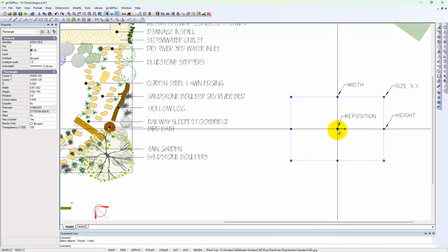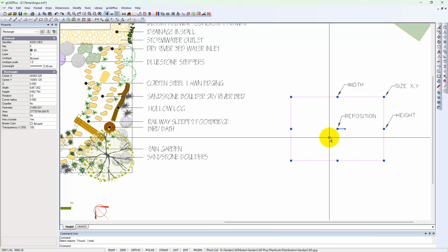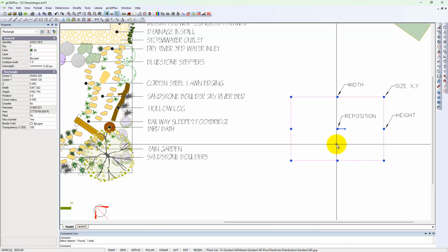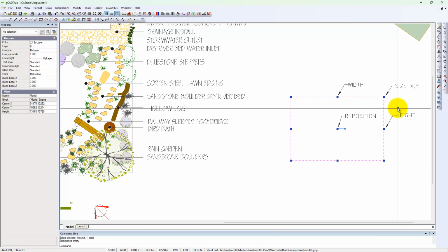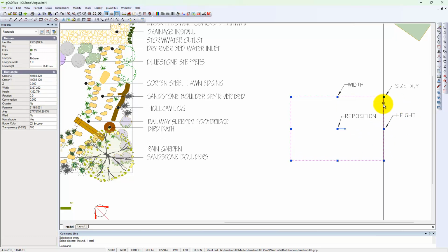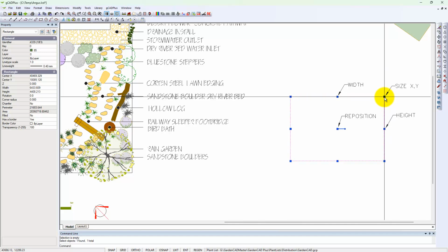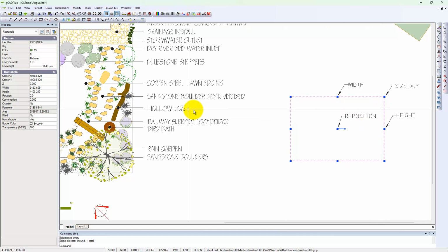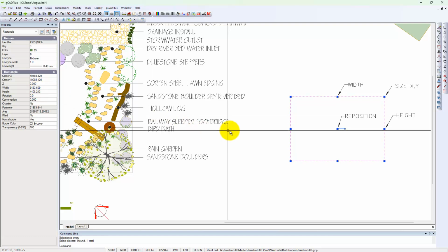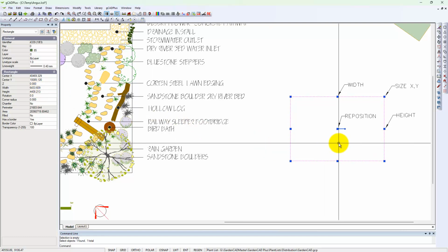The center grip enables you just to move the whole rectangle, but you can change the size of it just by grabbing a handle on the corners and moving away, and the rectangle will change size, the width and height, and that's over there in the properties box giving you the width and height. You can type the values in there if you like, and that would make a little more sense to edit in that way.